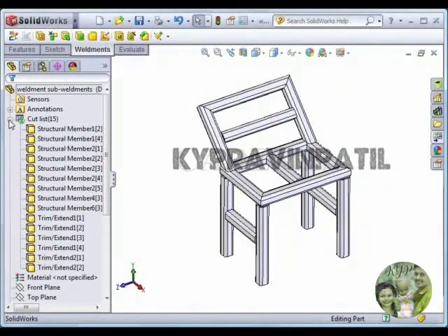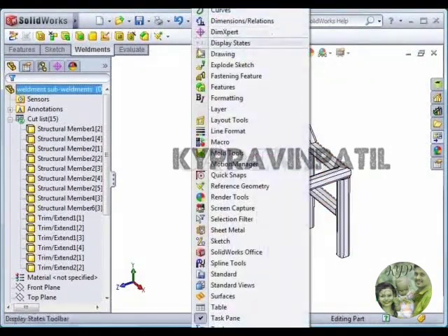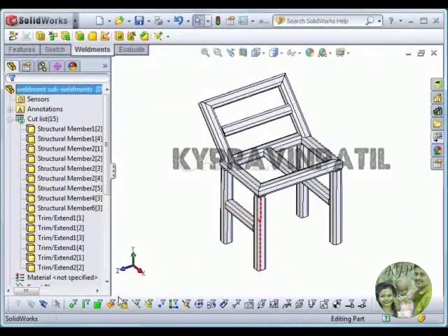Since items are difficult to tell apart from the list itself, I recommend enabling the solid body selection filter. You can do this by first activating the filter toolbar by right-clicking in an existing toolbar and enabling Selection Filter, then selecting Filter Solid Bodies.